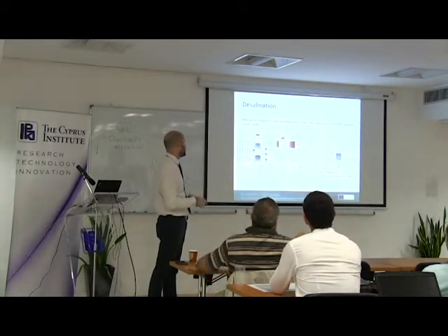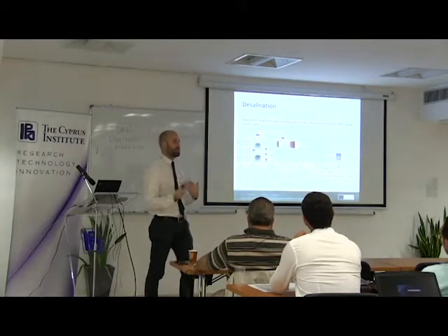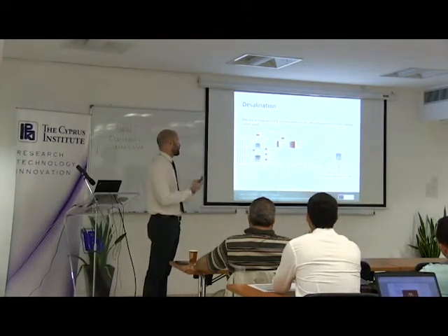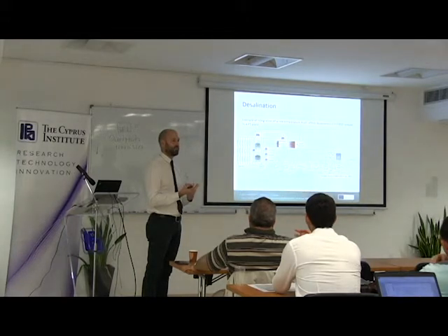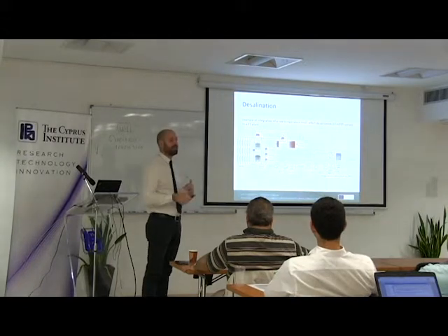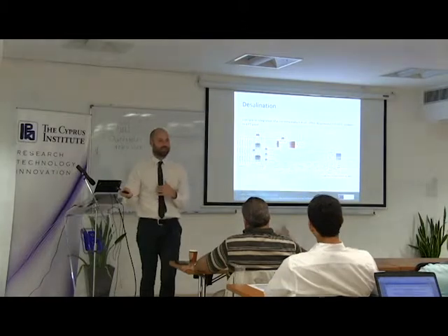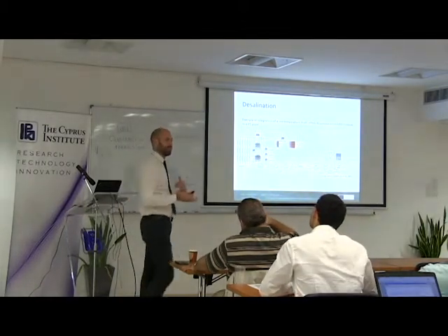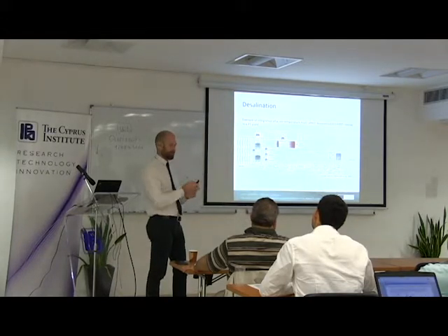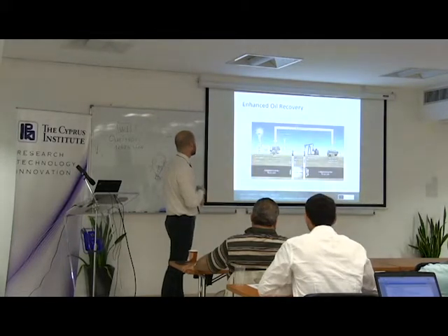The only point is that there is a good potential for coupling and using the waste heat, but this requires, first of all, increasing the discharge temperature of the steam from the turbine, thus lowering the efficiency of the power cycle, and then also building the plant close to the seaside, where usually the DNI is not always optimal. So there are some competing factors that must be considered. However, you're going to discuss this in detail next week, so let's skip.